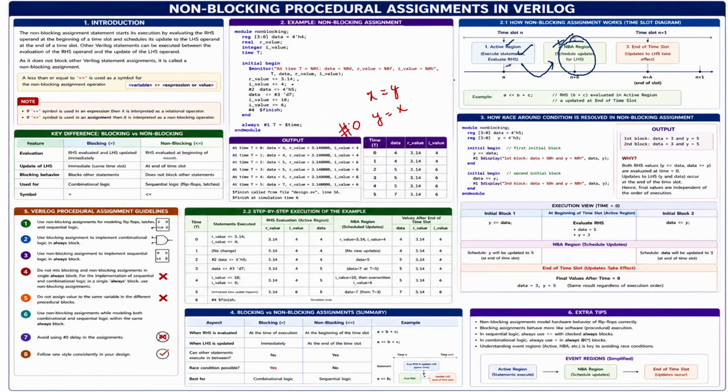Both the statements are executed at the same time, but a little delay will be provided. With the #0 statement, the statement will be executed after a slight delay, like a light-speed delay. We can't see that delay, but they execute at the same time, and we avoid this race condition by using the #0 statement. Also, we add it to the second statement, and that statement will be executed at the same time. So this is the step-by-step execution of your statements, whatever values we are giving.